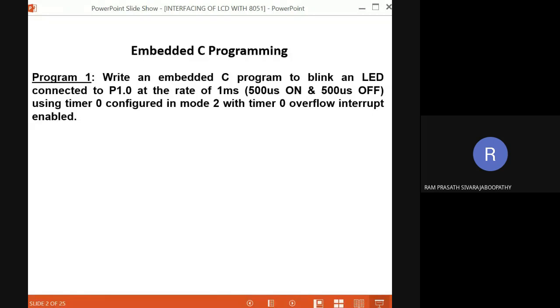Here for this, see, whenever you are accessing bit addressable SFR, you can go for bit operation. TMOD, it is not bit addressable. So what we have to do? We have to do in such way only. Fine? Coming to TCON and this IE register, okay, it is bit addressable. So what we can do?